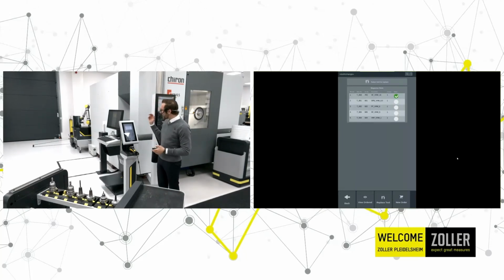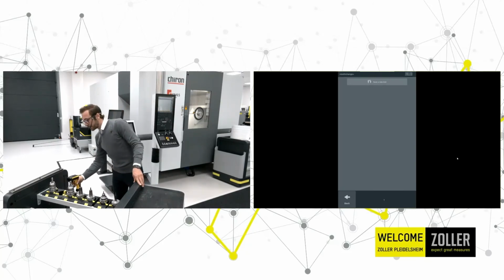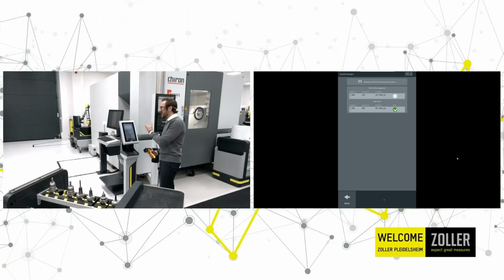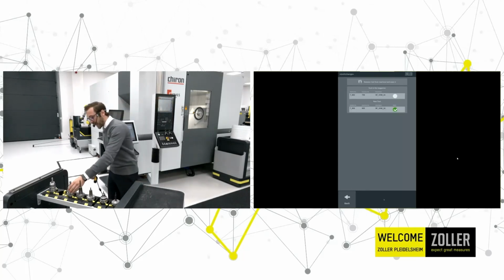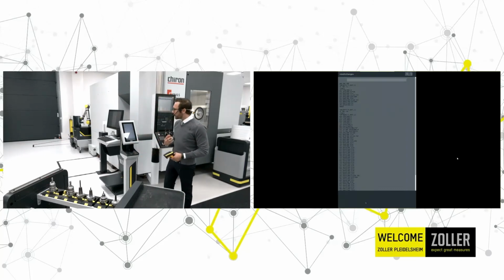So perfect. We want to replace here this tool, which did run out of lifetime. So I have marked it and I say replace the tool. So it wants me to scan the new tool. The ZOLLER code scanner software is recognizing immediately the spare tool or like the old tool. So I scan this as well. So you see there is no chance to do any mistake for me as an operator.